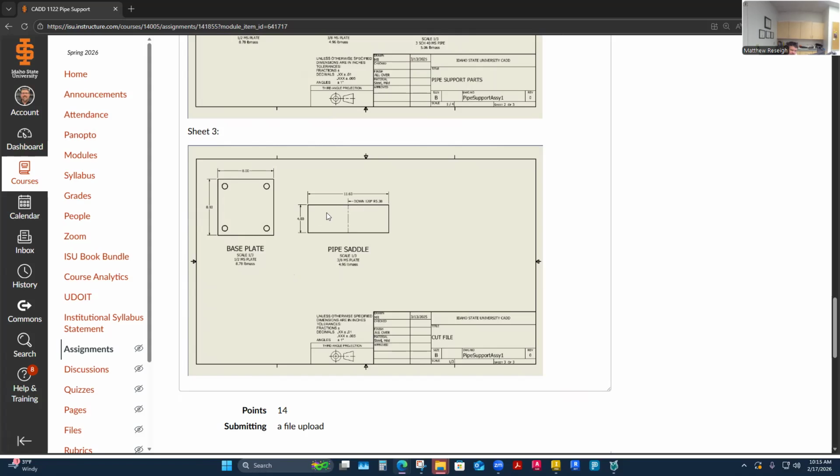Press braking leaves creases in it, and rolling it will be smooth. But rolling 3/8 plate, not all companies have heavy enough rolls to do that if they're just a sheet metal shop. But 8x8, this just helps somebody quickly identify. And I don't even put on any center marks here at all.